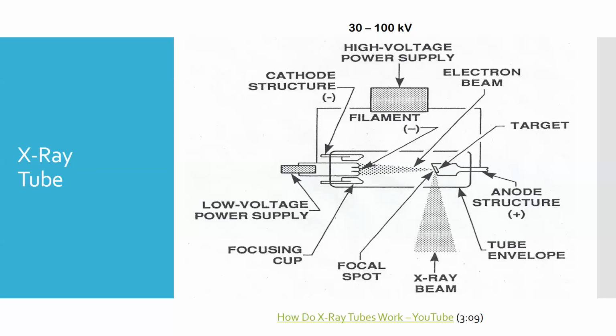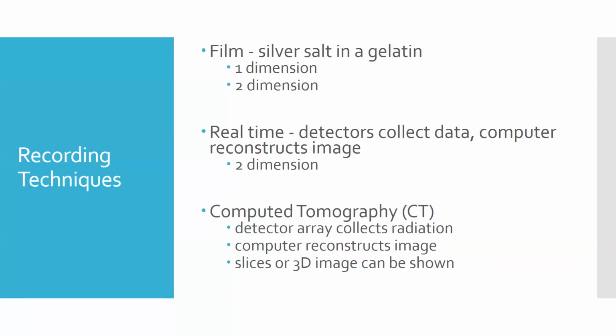And so if we see one of these in operation, it's going to look something like this. Let me pause this. Okay. So we've got two different ways to have our radiographic source, right? Our gamma material and then our X-ray. Whether it's the photon radiation of X-ray or the gamma rays that come off of a gamma radiography source, it is going to pass through our object, and then we're going to use some kind of a detection method to see them on the other side.